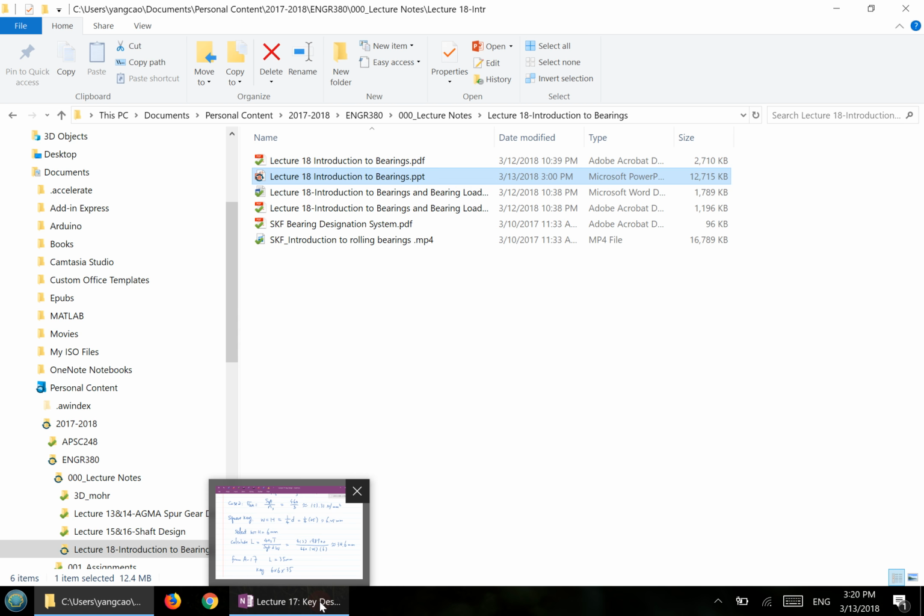When keys fail, they're sheared along that path, aren't they? Could be, yeah. But I guess because it's so small, you can argue that instead of using that area, you can use the straight line, just because the arc angle is thin enough. They'll be close enough. Exactly. So we just approximated it as straight. Very good. Okay, awesome. Thank you. You're welcome.